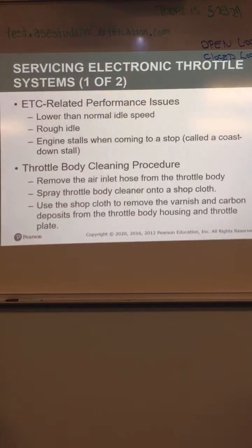You can control the idle speed with the scan tool on these types of vehicles. You can make the throttle open, you can control the idle speed, you can put it pretty much wherever you want it. Performance issues could be lower than normal idle speed, rough idle, or stalls when it comes to a stop, called coast down stall.